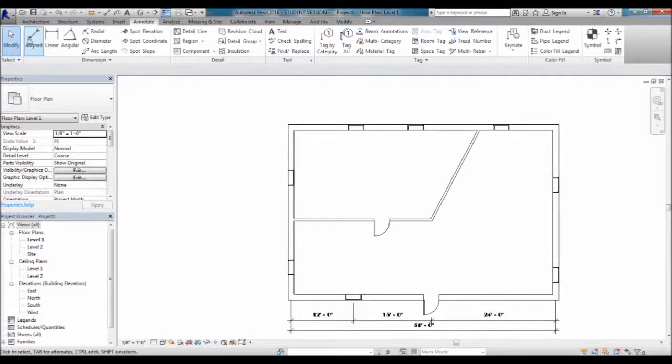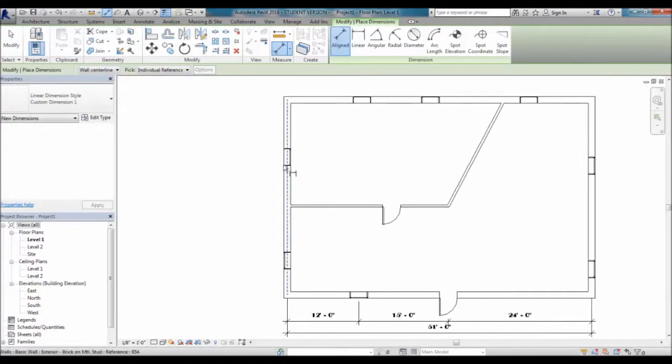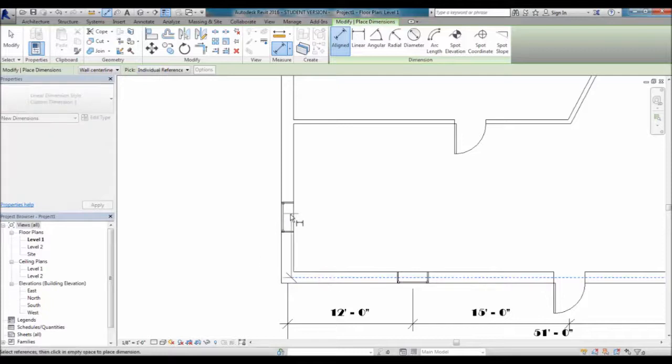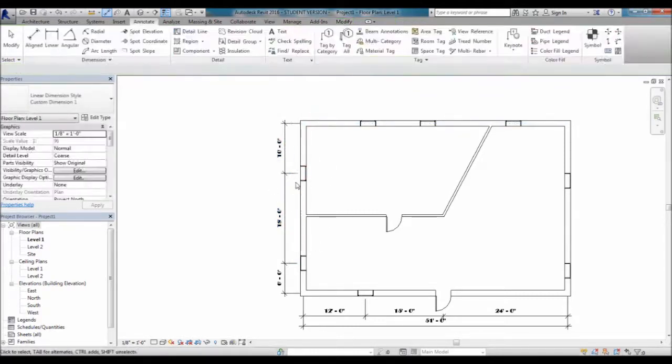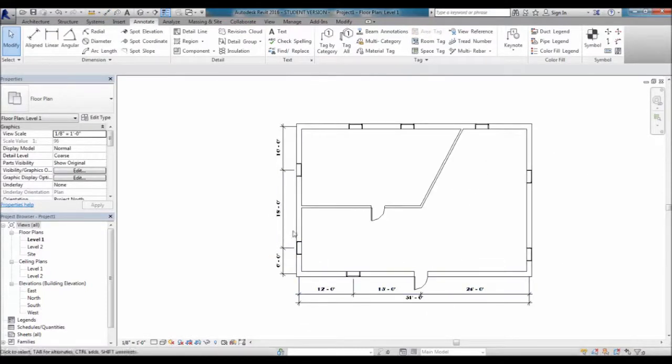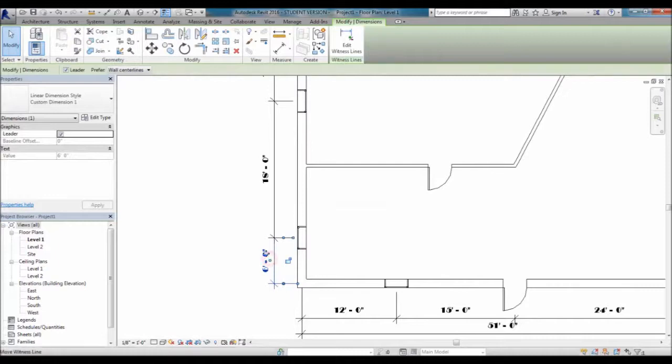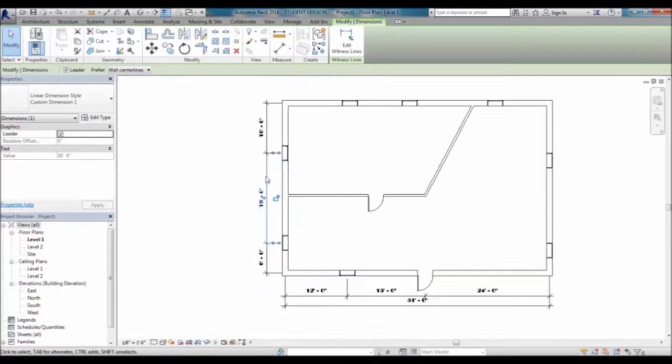Whereas if you were to draw dimension lines, let's say if we wanted to dimension this side here with these windows, if we were to draw dimension lines from this to this window, all right, clicked out here and placed it, right? So now that is its own one single dimension line, and then drew another dimension from here to here, right? Clicked and placed it, did the same right there, okay? Now the difference is that you still have the dimension between all three of these, but if you click on it, you'll notice that it highlights one individually every single time, all right? And so obviously they're not connected to each other.